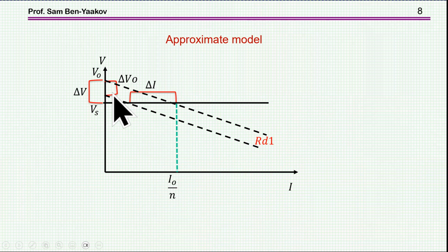Now, if we have a droop, then as the current builds up, the voltage of the power supply will drop, and this will be the drop in the voltage of the output across the load. Now, the current deviation between the two power supplies is this value here between these two points. For this particular voltage level, this is one power supply, the other one, and here is the deviation, and I'm assuming that this is like the nominal value, the total output current divided by N. In this case we are talking about 2 units, of course there could be many more units.